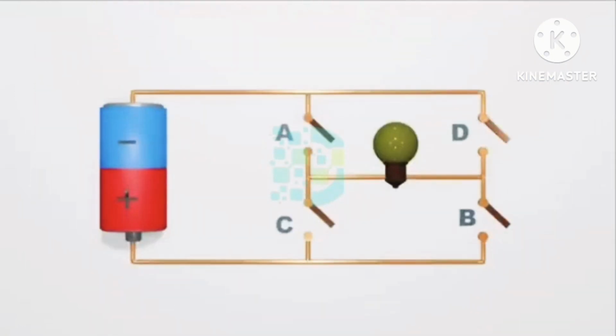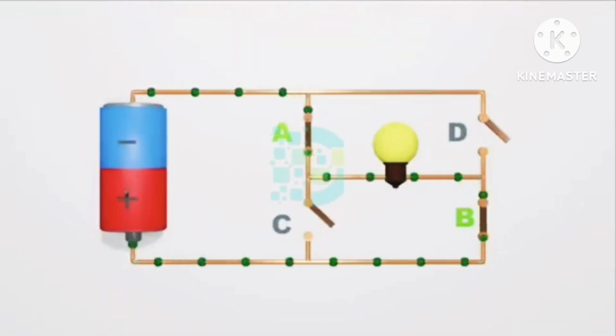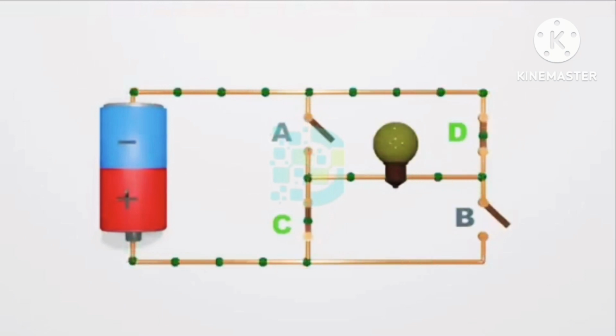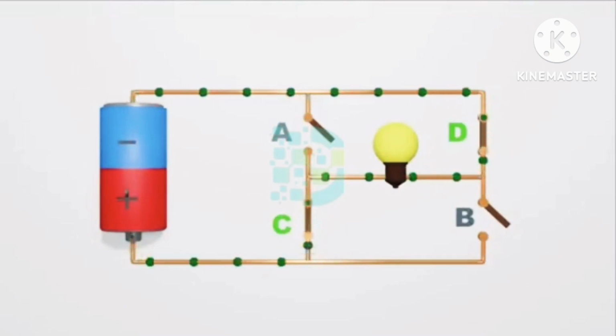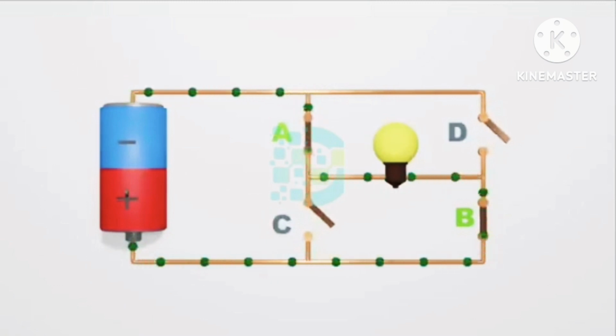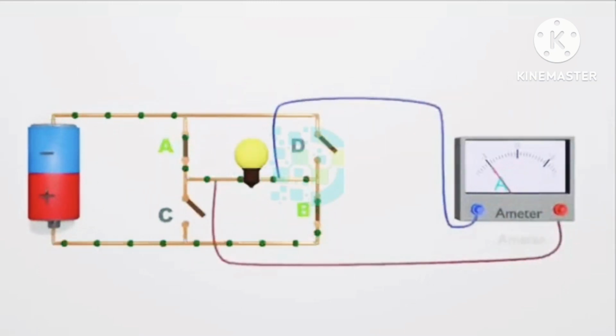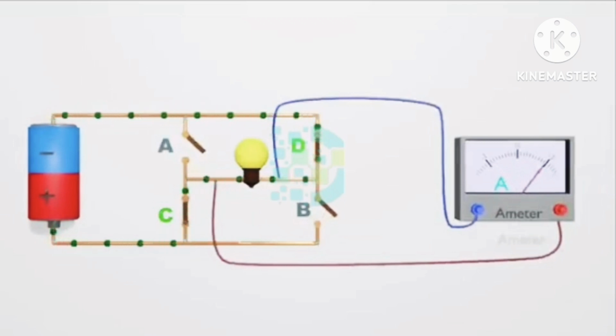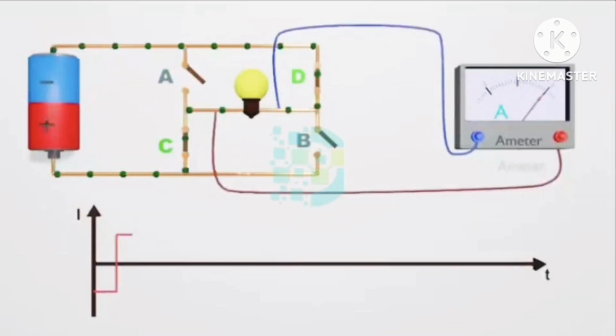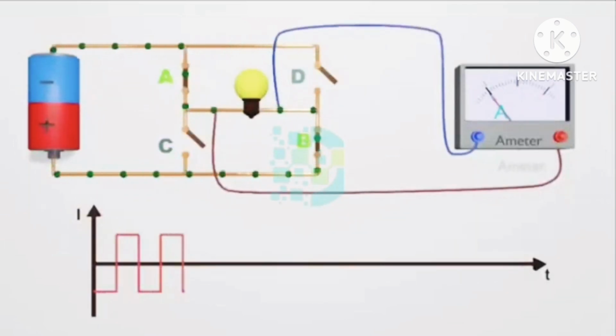Instead of swapping the wires, we can do this by using 4 switches. Switching your current in a given manner on and off, very rapidly, would give pulses of direct current. We call this an H-bridge arrangement, which would do at least half the job. To make proper AC, you'd need a switching H-bridge arrangement that allowed you to reverse the current completely and do it about 50 to 60 times every second.